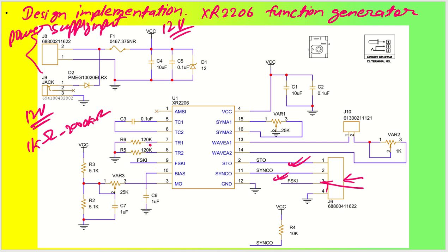Now, why we put this RC is that it is actually going to give you your output frequency. The output frequency will be measured with 1 by 2 pi RC. That is the formula that will be utilized to give you the output frequency at this particular point.